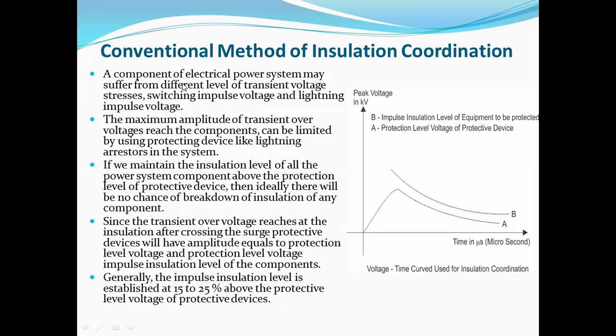Right, for this purpose we are using arresters. So if we maintain the insulation level of all the power system components above the protection level of the protective device, then ideally there will be no chance of breakdown of insulation of any component.